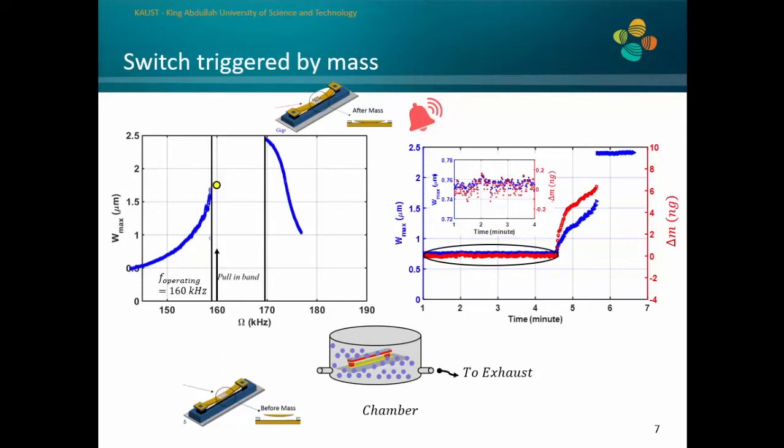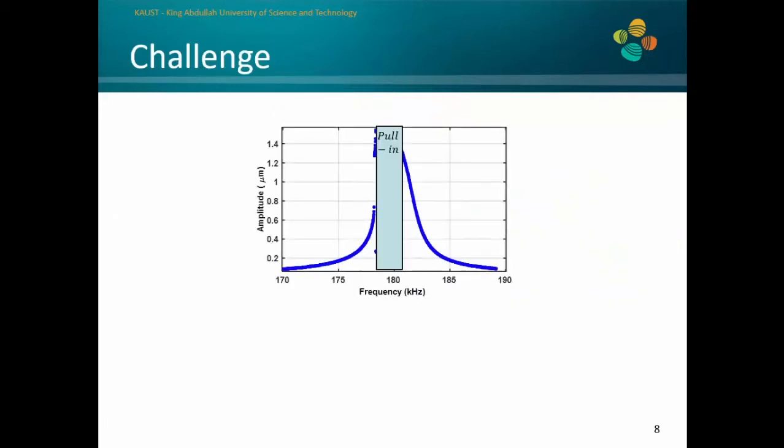Now, the challenge with this technique of using a single mode to operate this device is that there is a problem of stability near the bifurcation point. As the frequency approaches the bifurcation point or the pull-in instability, the noise effect becomes really significant, and it might cause switching not due to water vapor adsorption, but due to the noise only. As you will see here, operating the resonator away from the pull-in instability, we have a stable response.